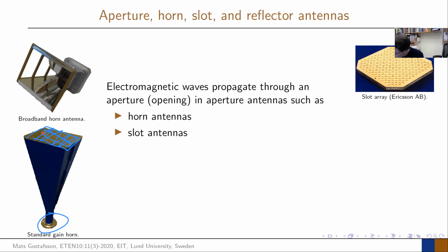And of course, when you look at this one, you can see there are some holes. But even if those holes are there, the real aperture, when we think about it, is still this piece here. The holes can simplify the manufacturing and reduce materials, removing pieces that don't really matter. Almost all the radiation in these antennas is still passing through this aperture that sits here. So it's also an aperture antenna.